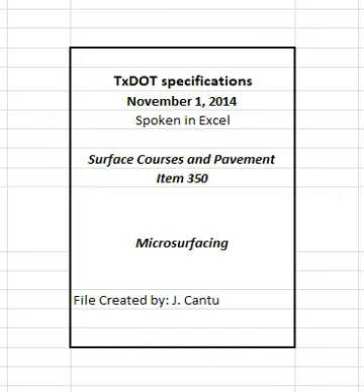2.3 Mineral filler. Provide a mineral filler that is sufficiently dry, free-flowing, and free of clumps and foreign matter consisting of non-air entrained cement meeting the requirements of DMS 4600, hydraulic cement, or hydrated lime meeting the requirements of DMS 6350, lime and lime slurry. 2.4 Water. Provide water that is potable and free of harmful soluble salts. 2.5 Other additives. Use approved additives as recommended by the emulsion manufacturer in the emulsion mix or in any of the component materials when necessary to adjust mix time in the field.